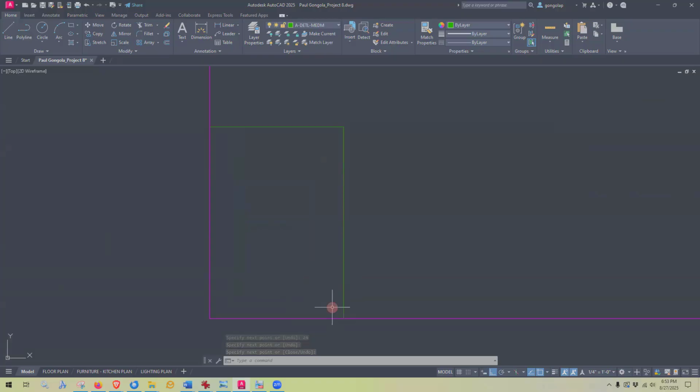Let's put the toe kick in. So I said before that the toe kick is always 4 inches high. Not always, but most of the time it's 4 inches high and 3 inches deep. So let me just go to my line tool, O track up 4, draw a line to the left 3 inches, and then come down. And then I'll just trim this out here.